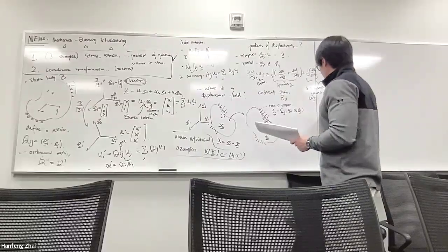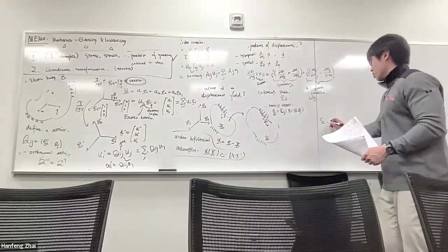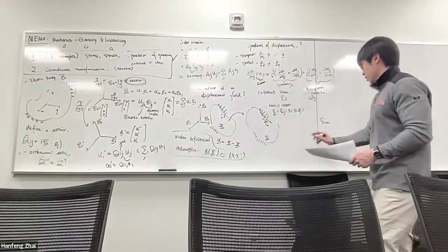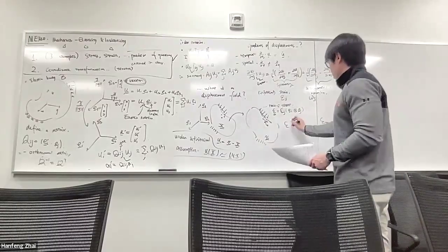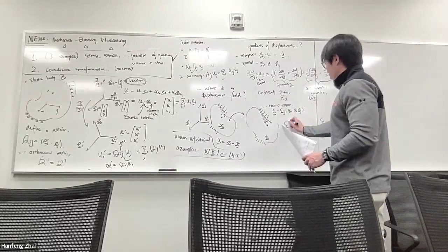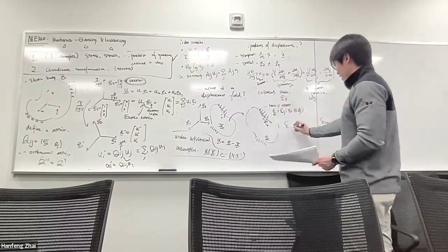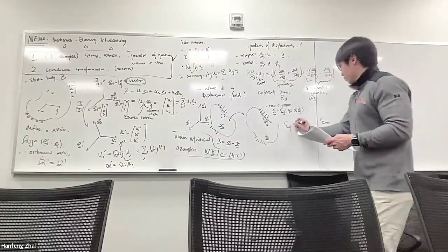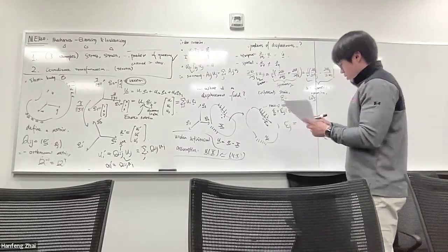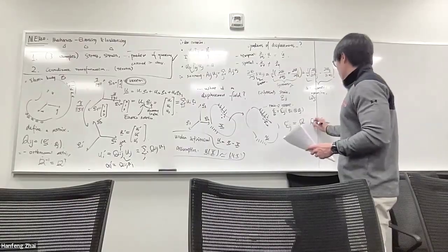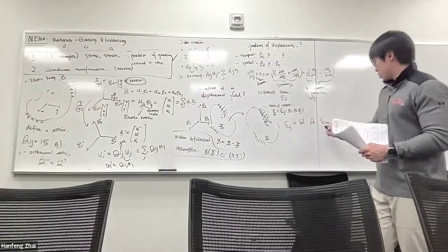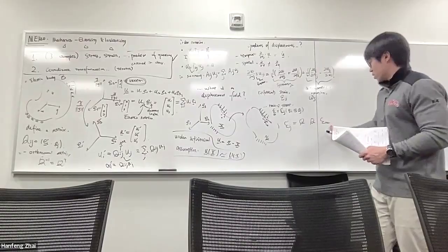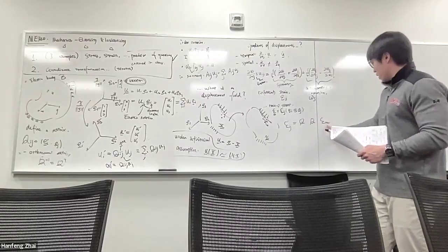So let's say we have a strain tensor under the coordinate system mn, and then I want to transform the coordinate system to represent the same strain tensor into epsilon ij. The transformation process can be written down as two rotation matrices applied to the two indices, respectively, m and n.